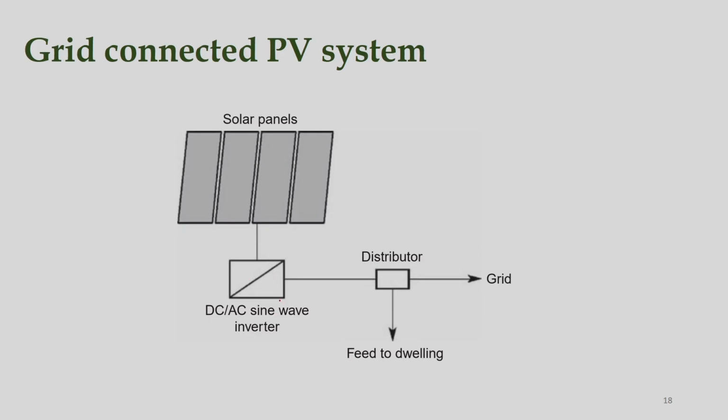The primary purpose of the inverter is to convert direct current to alternating current, and when MPPT is introduced in those inverters, one more purpose of the inverter is to maximize the power, so that at all solar insolation levels maximum energy can be extracted.